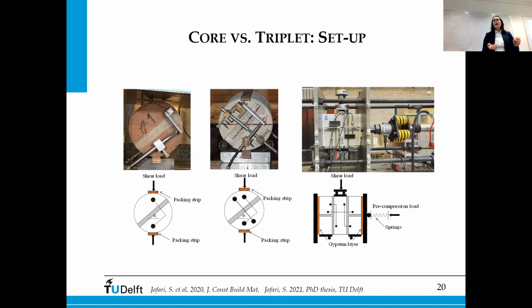Well, it's another nice tool, but if you want all the input parameters for this kind of model, you need to do too many tests. The question is more generic: why are you using a homogenized finite element approach instead of a discrete cracking approach? Because for the discrete cracking approach, you still need to enter, for instance, the softening in shear. If you are able to get it out from the cores, then that is good.